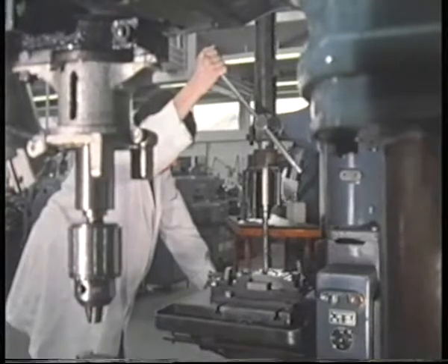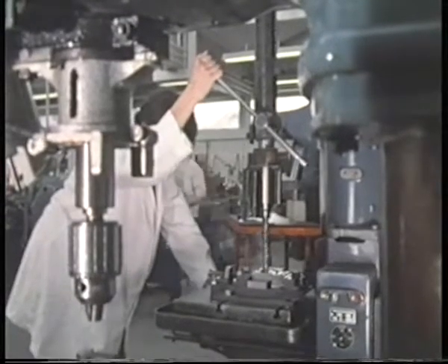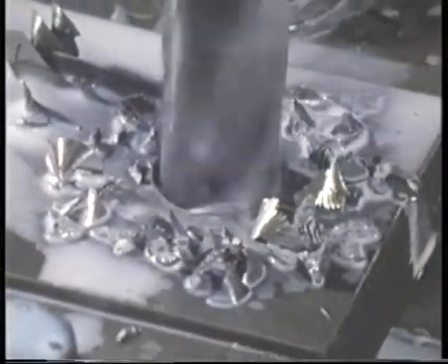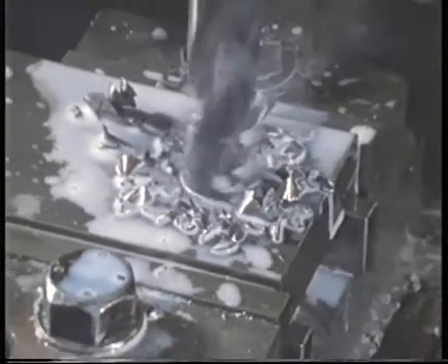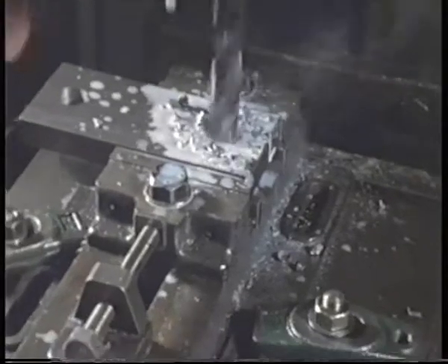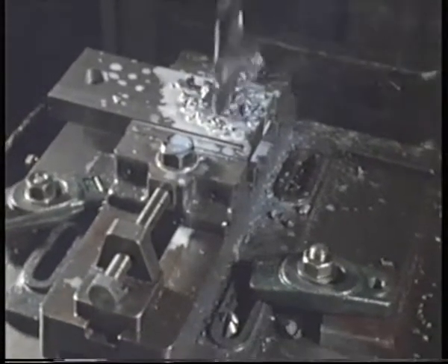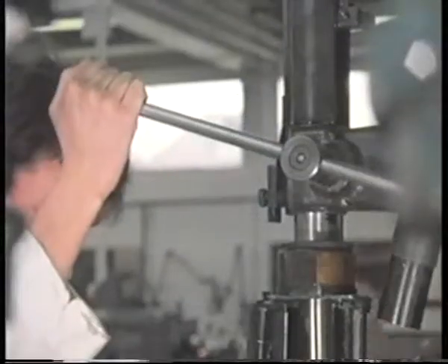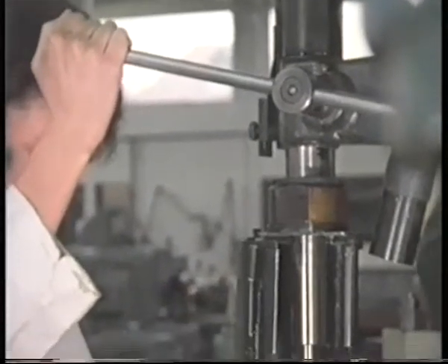Vertical drilling is a process where only the cutting tool moves. It rotates, generating a hole in the component. The component can't move, it's clamped in a vise fixed to the machine table. But there's more to it than that. The rotating drill must be fed or traversed into the work in order to cut.